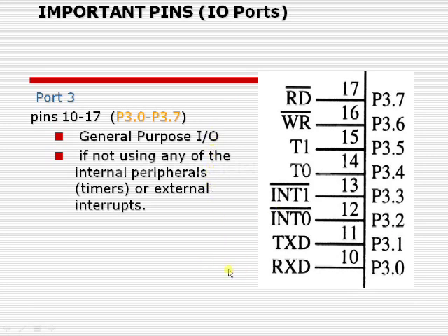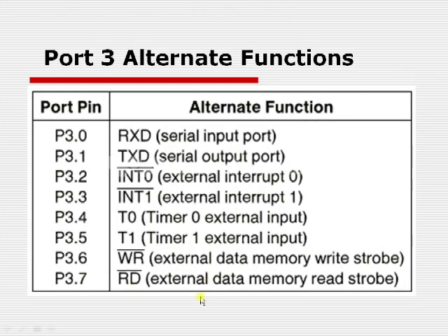So this is how we are going to use all these port pins. If I want to use any of these port pins as output, then we have to write some logical values into those port pins. Why? Because each and every port is provided with 8-bit flip-flops or an 8-bit register. Every pin is associated with a single flip-flop, therefore a complete port is associated with a register.